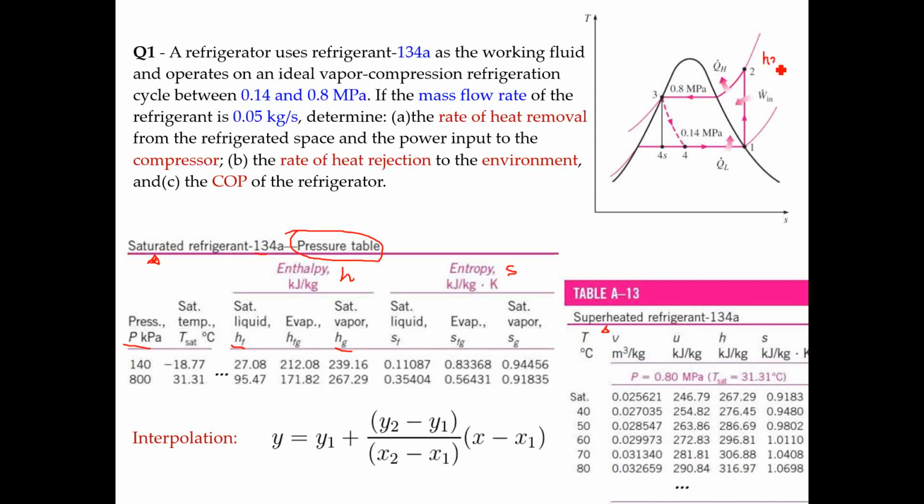So here is when you need to do the interpolations, because as we just reviewed, there is a very important parameter that controls where you should locate point 2. So whether it's H, S, or temperature, I will leave it to you to try. But with this table, basically you need to utilize your S values and do the interpolation in between these two.